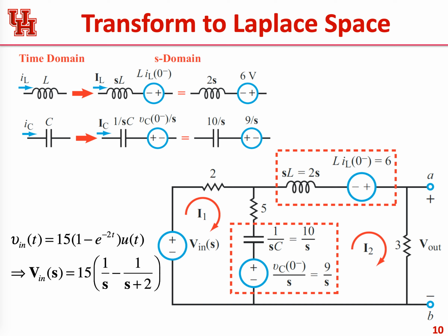So again, this circuit here, which is our part 2, contains all the information from the early part of the circuit, where the voltage was a fixed 15 volts, all the way from minus infinity to 0. It contains that information in the form of these 2 initial conditions. It's encoded in that. And then it also contains the input that has been applied, and that's part of this formula here. So all we need to do is apply this input to this circuit and then solve for it.